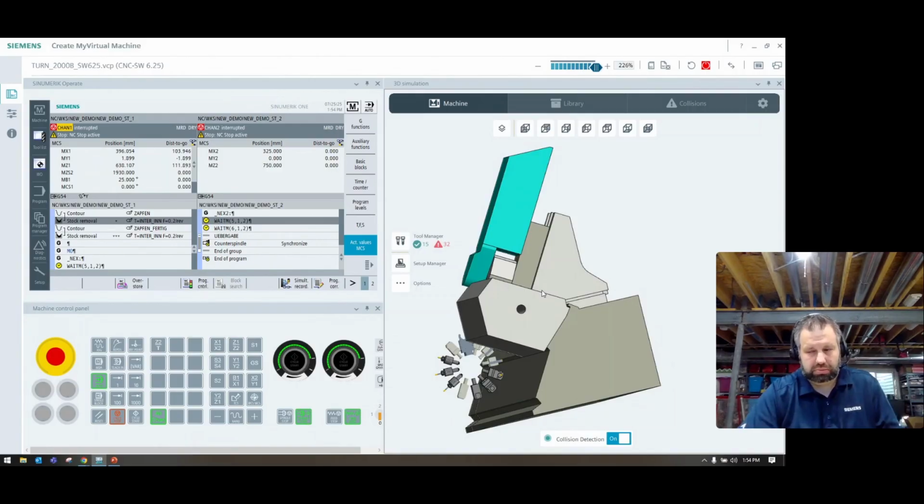Yeah, absolutely. I would completely agree with that. Just about every time I've had to legitimately do interpolation turning, outside of a machine like this where we're doing compound angle interpolation turning, it's usually on some big massive horizontal boring mill. They had some kind of boring journal, an ID, and they wanted to be able to blend a chamfer or radius into that bore.